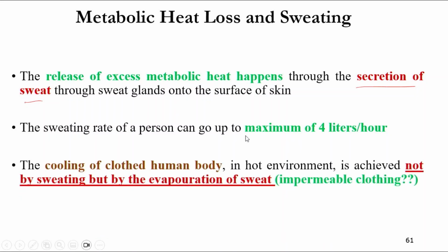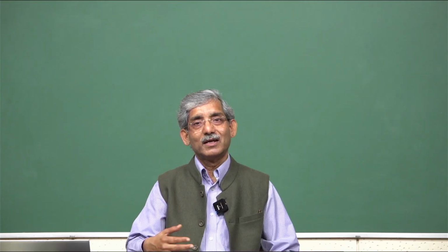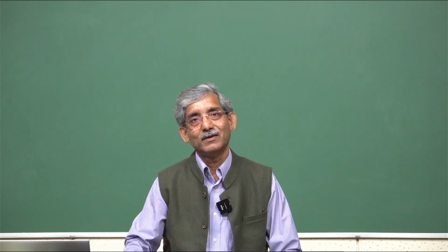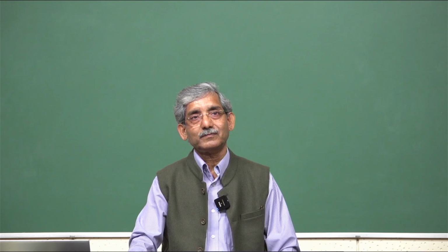The cooling of a clothed human body in a hot environment is achieved not by sweating but by evaporation. If sweat does not get evaporated, like in an impermeable PPE kit, or in coated or laminated ones, then evaporation is not there, and the problem will be heat.